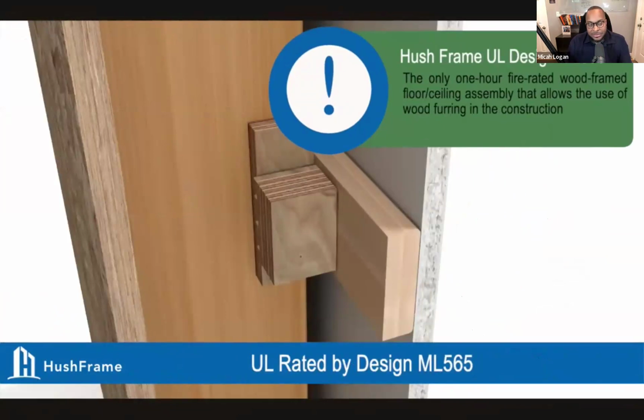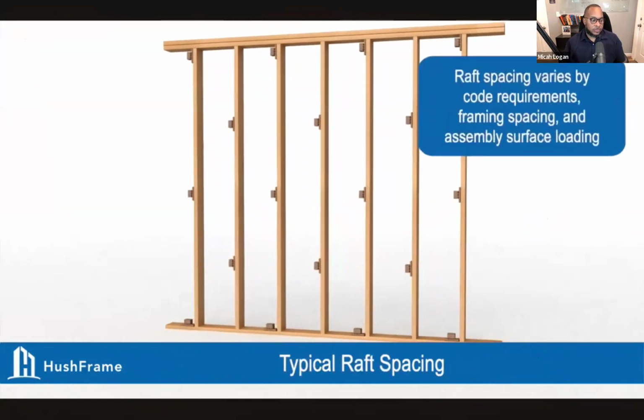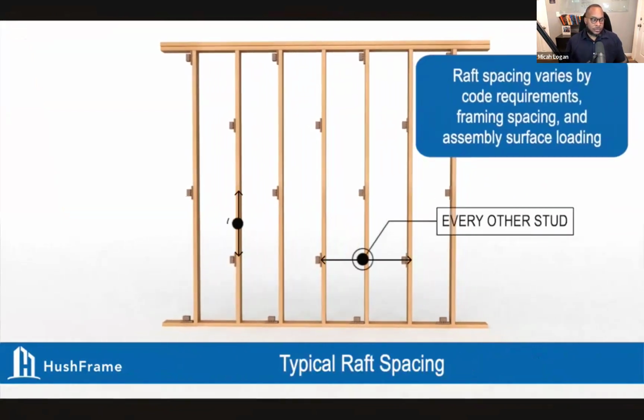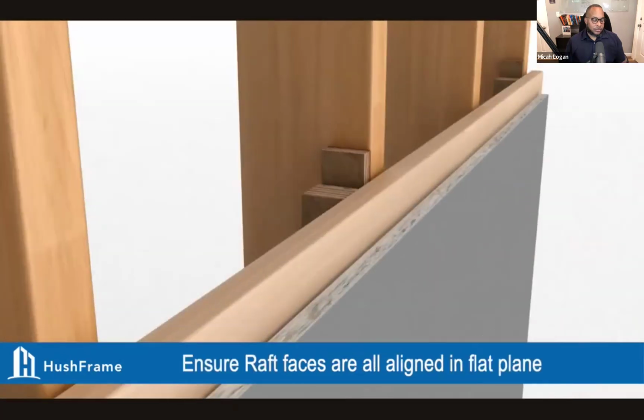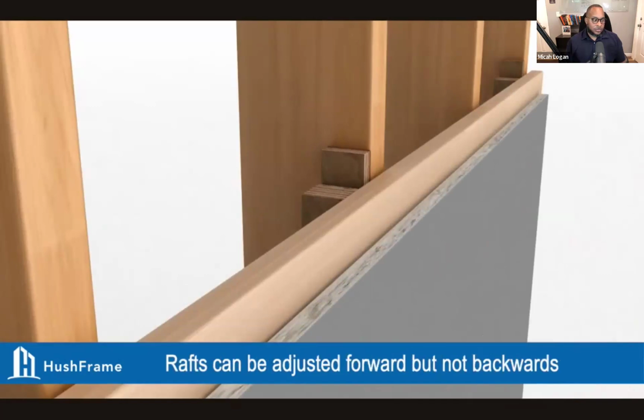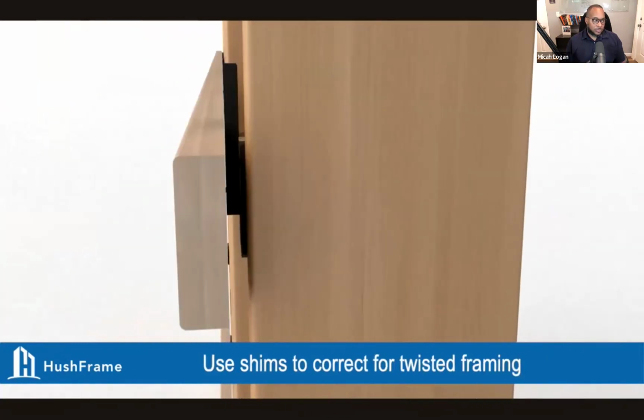HushFrame UL Design M565 is the only 1-hour fire-rated wood-framed floor ceiling assembly that allows for use of wood furring in the construction. A typical installation grid will have the raft spaced every other stud horizontally and every 2 feet vertically. Ensure the raft faces are all aligned in a flat plane. The rafts can be adjusted forward but not backwards to correct alignment of deflected studs or joists. Run a string or laser line up to the rafts. Use shims to correct mounting on twisted framing.